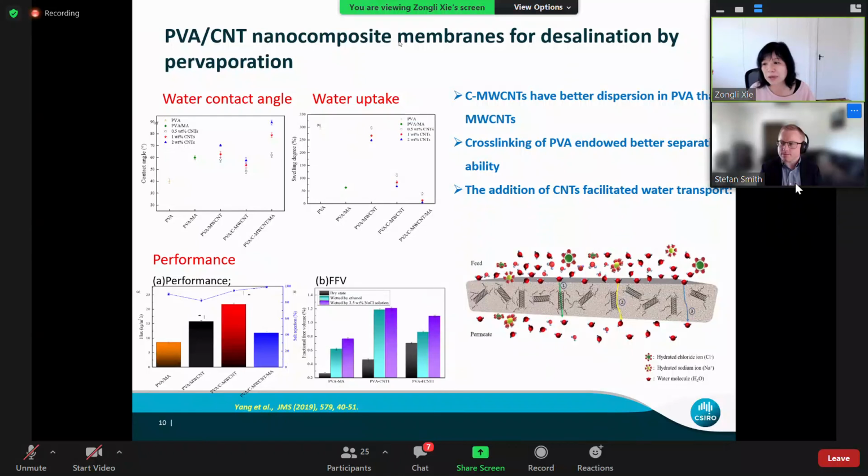And then back to your first question, it's carbon nanotube dispersion. It is very difficult, in particular in water. So we did use some sonication, and that's also why having the functionalized group helps the dispersion. It helps maintain the dispersion for a longer period of time. And that's the reason we introduced acid treatment in the later work, again to help improve the dispersion.